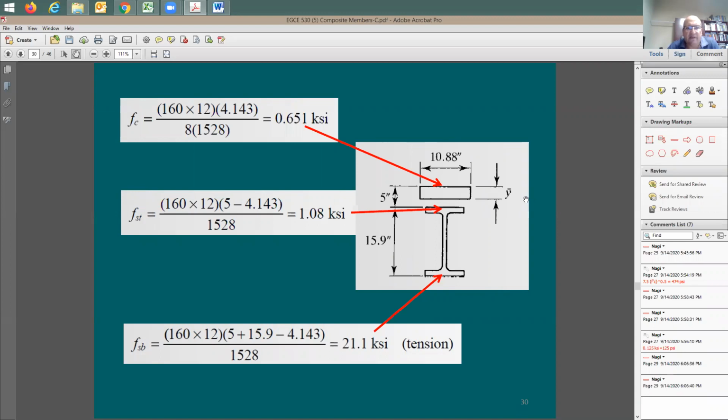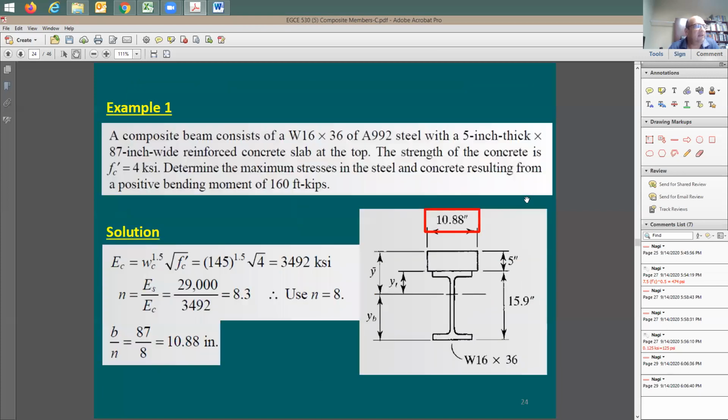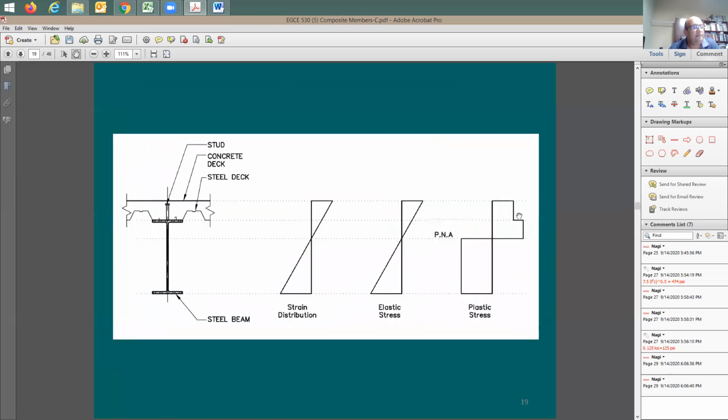because in some cases you do a check based on the plastic distribution. Now someone's going to say, what plastic distribution? I'm going to say like this that we have discussed, like in here, like the standard design case. And after you do this analysis, you don't like the results. Now you can go back and do actual stress analysis within the beam and see if your beam is going to be in a good shape, or no, I don't like it this way. So basically, the elastic stress analysis is used in a case like this.